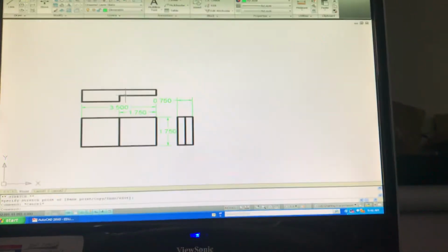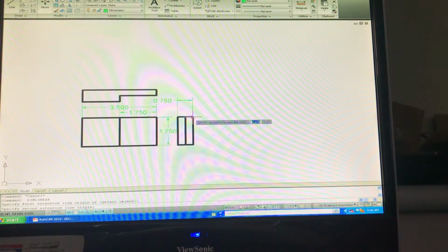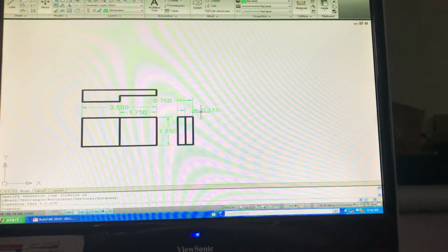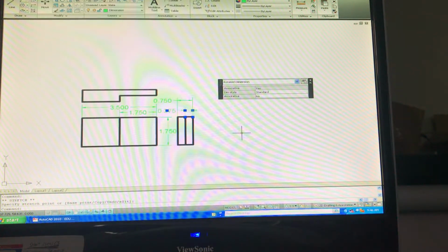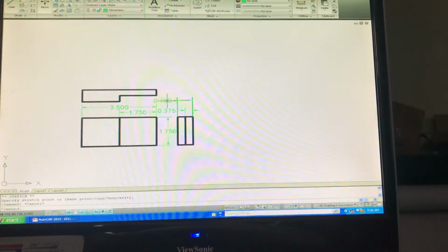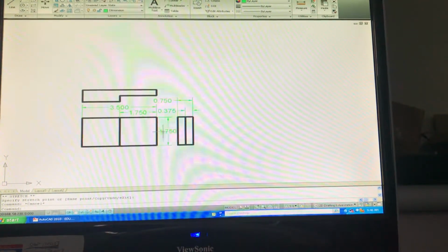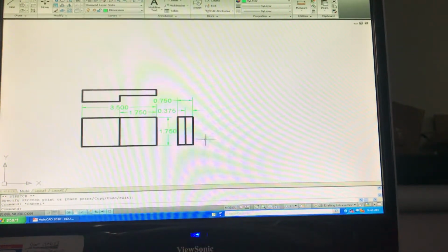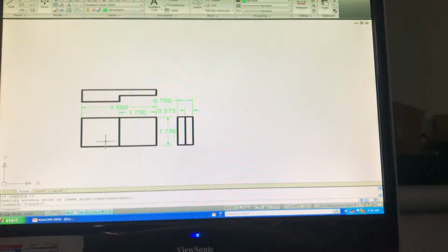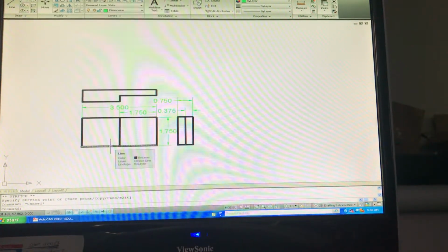So within our multi-view drawing. And again, full length measurements go outside or on top of shorter length measurements within an object. I never put a dimension inside my views. I want those views clean. Does that make sense?